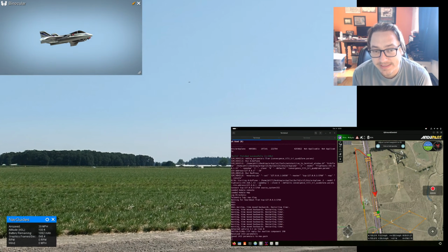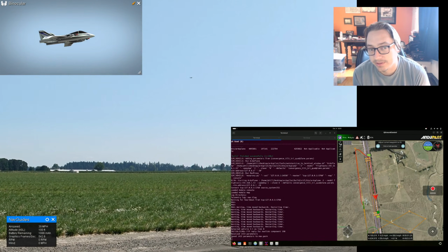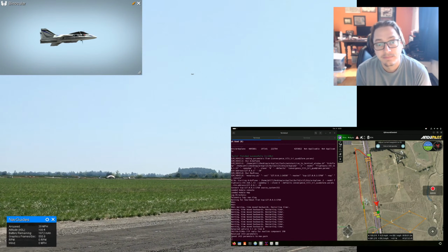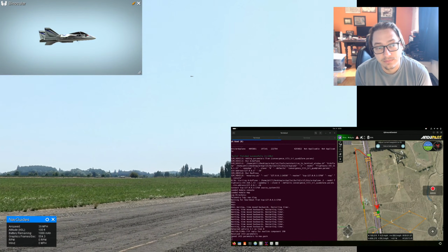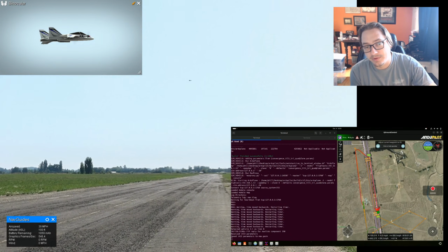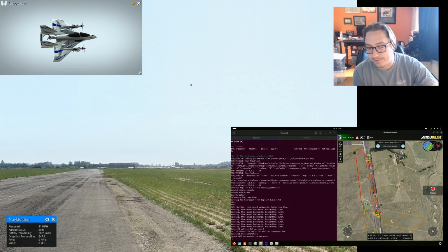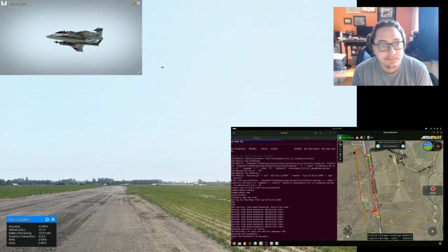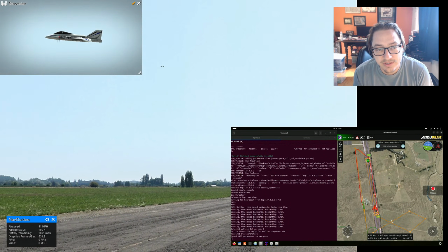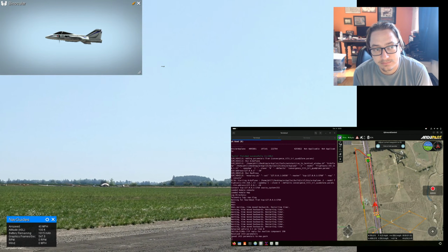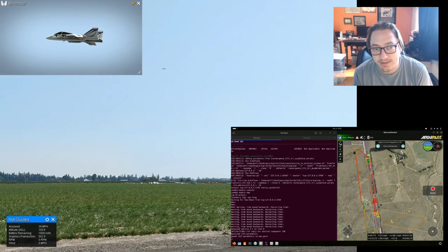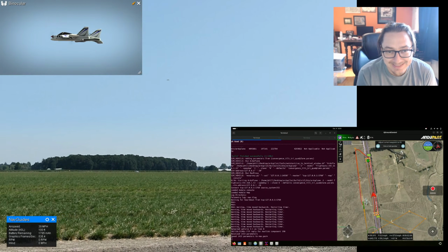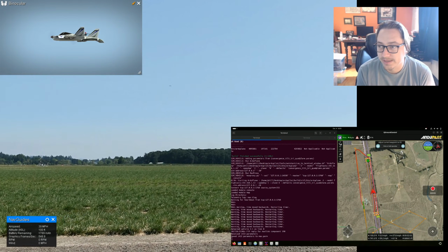So all the while that it's doing this, it's sending commands to the onboard camera to, well, it would be. I didn't actually do that because we don't have a virtual camera, but the drone mission would be programmed to take photos every however many feet or seconds you want, as it goes. It saves them to the onboard computer and plugs the GPS telemetry data into the metadata of each photo so that you have exact coordinates of where each photo was taken.